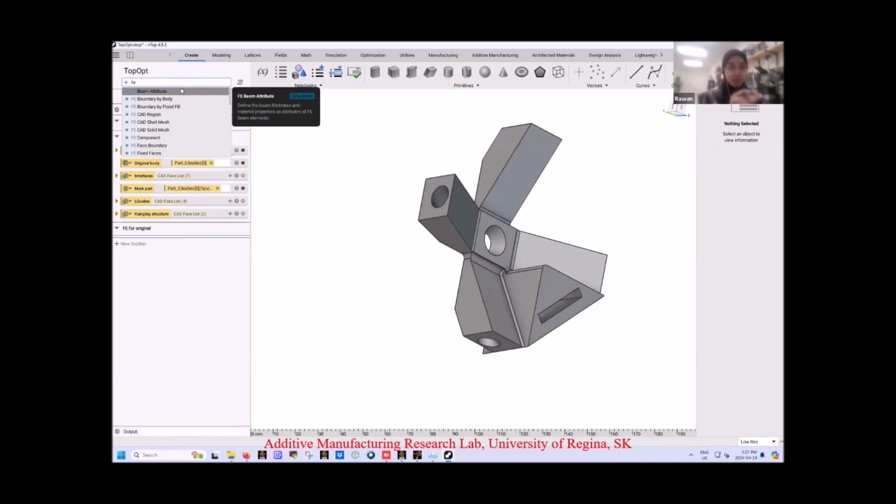The first approach is top to bottom, where you go from the mother block, which is the FE mesh itself, and then go step by step to see what kind of input is needed in each block. And the other one is to start from bottom to top, where you start with the simplest part and then keep adding blocks after each other. But for the bottom-to-top approach, you have to be really experienced, and you have to have good knowledge of the blocks needed as a next step.